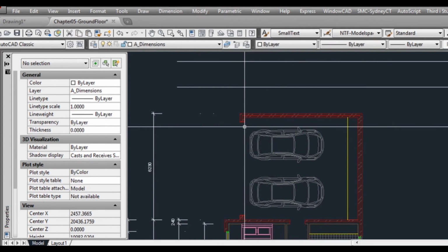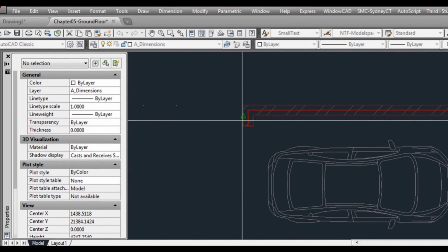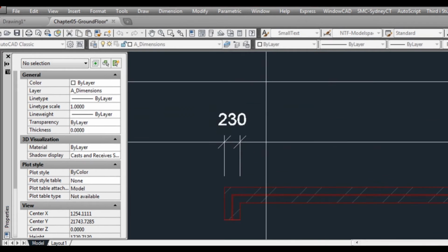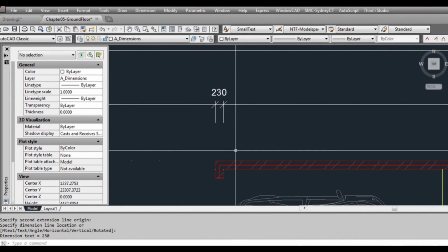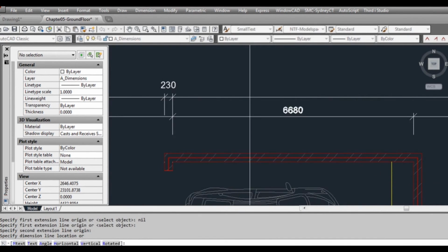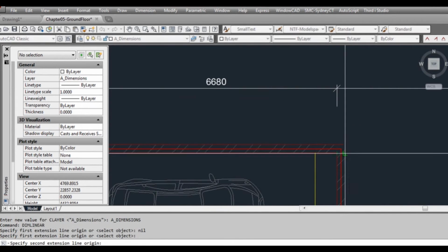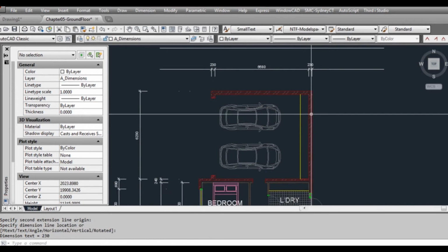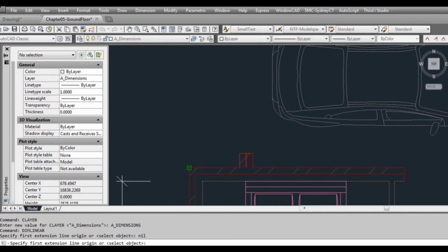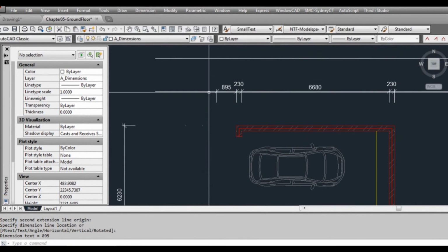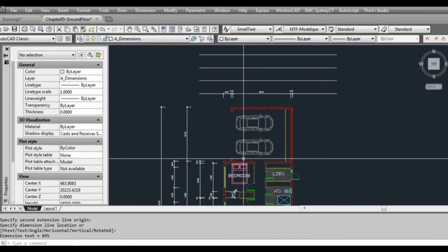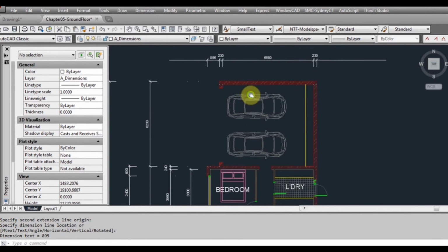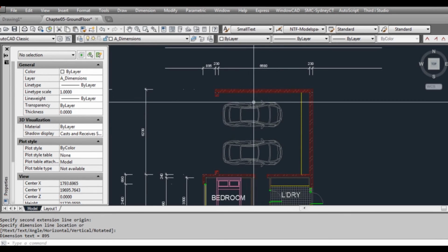Okay, and with these garage walls, these are 210 mil. Oh, sorry, 230 mil. So that's 2 110 brickworks with a 10 mil cavity. So these are sort of basic things for dimensions in Australia anyway. Your country may be different. You might build completely differently. I don't know. I've seen some different things internationally. So just apply these sort of same ideas to your own country dimensions and for material thicknesses.